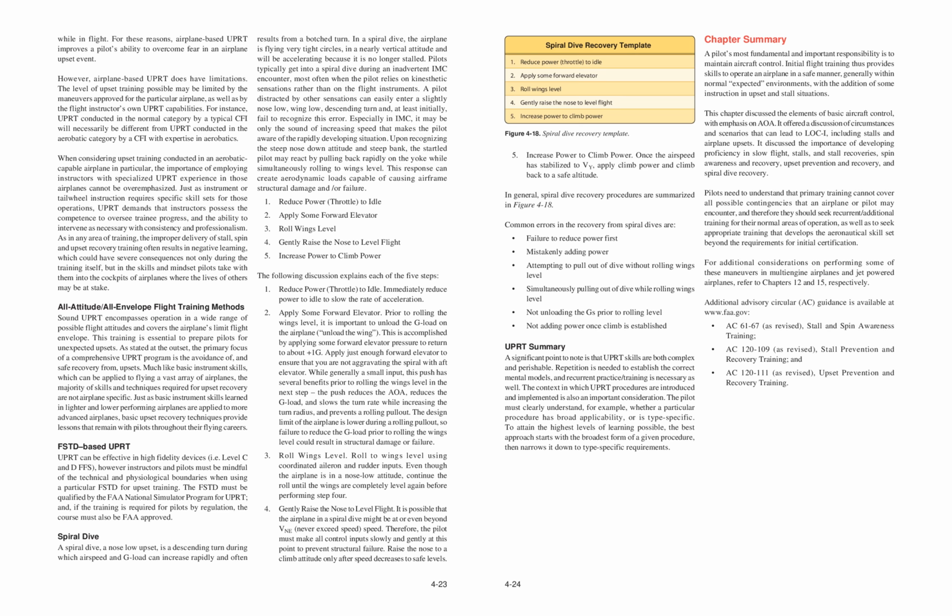Especially in IMC, it may be only the sound of increasing speed that makes the pilot aware of the rapidly developing situation. Upon recognizing the steep nose-down attitude and steep bank, the startled pilot may react by pulling back rapidly on the yoke while simultaneously rolling to wings level. This response can create aerodynamic loads capable of causing airframe structural damage and/or failure.